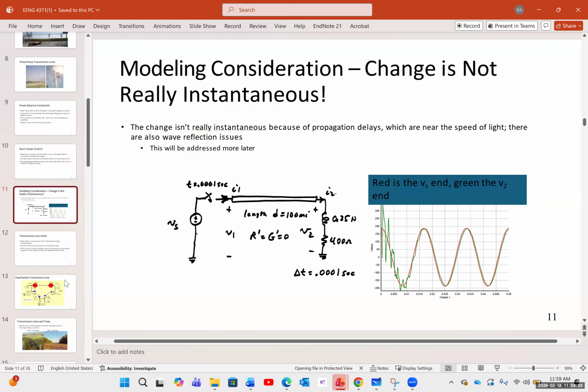Now, one important factor, as mentioned, in the limitation is sagging. Therefore, we need to have the maintenance on transmission lines. And one very important thing is trimming, and you've seen this a lot. The reason that we trim these trees, and there is a standard for it, is to prevent those accidents and blackouts from sagging.